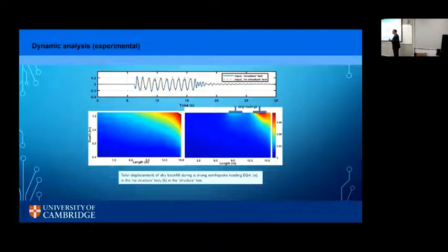This may not do the structure any good, but what it tells us is there's a big interaction going on between the structure and the kind of deformations you get. Now, imagine you're going to use your self-healing soil improvement techniques. What's important then is that you need to improve this area a lot more, and you don't need to keep improving the whole backfill.